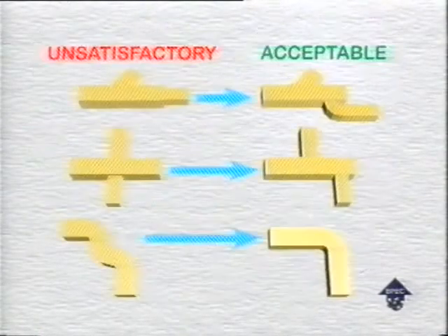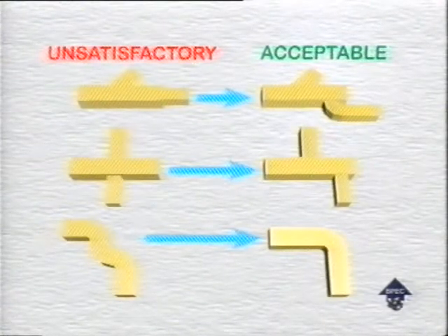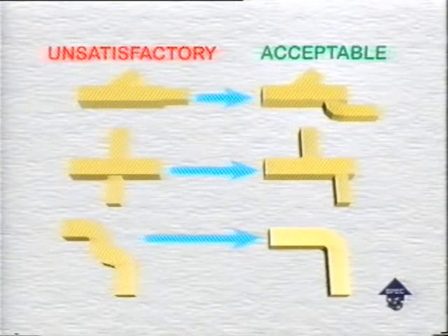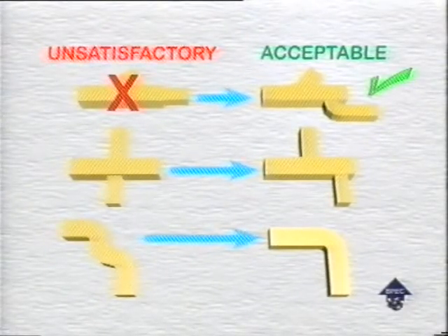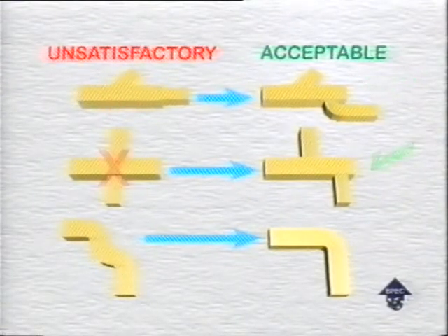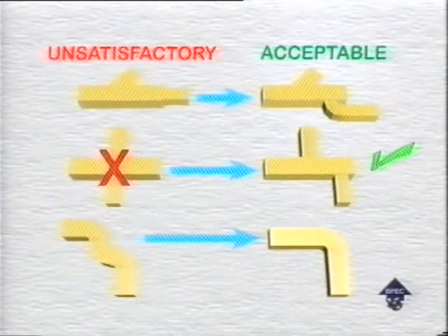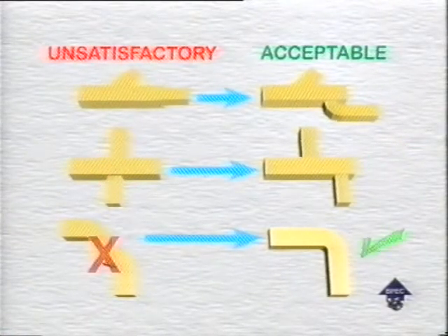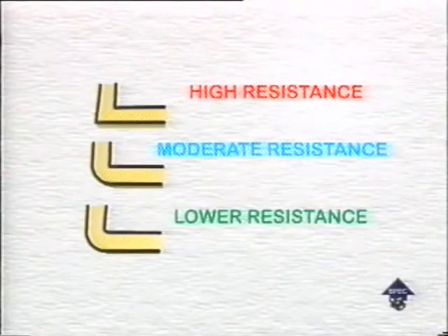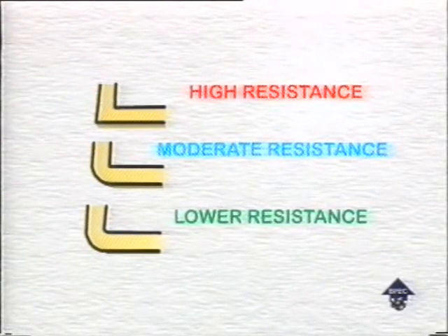If you have to extend ducting, there are some do's and don'ts to remember. Wherever possible, connect new ducts directly to the plenum. Connect new ducts to the sides, not the end of existing ducts. Don't fit a new branch directly opposite an old one. Design for as few bends as possible. And remember that square bends present greater air resistance. One final point about ducts. Just like water pipes, they should be insulated.